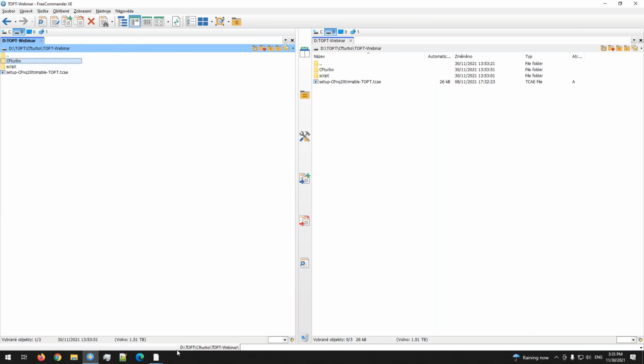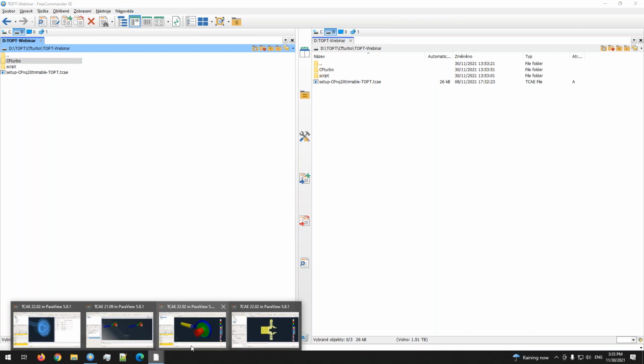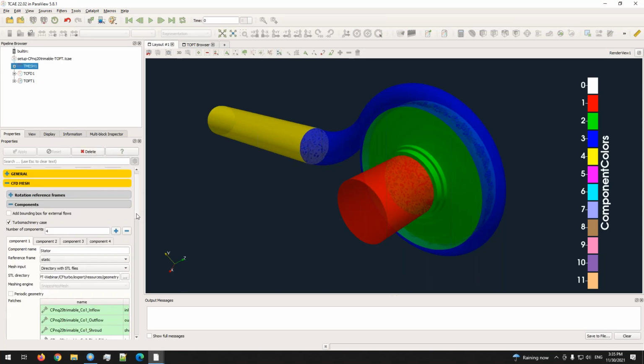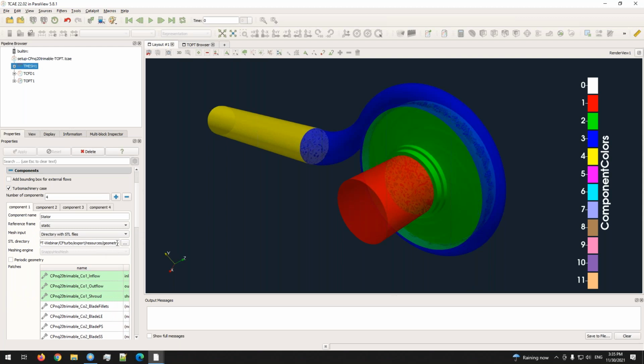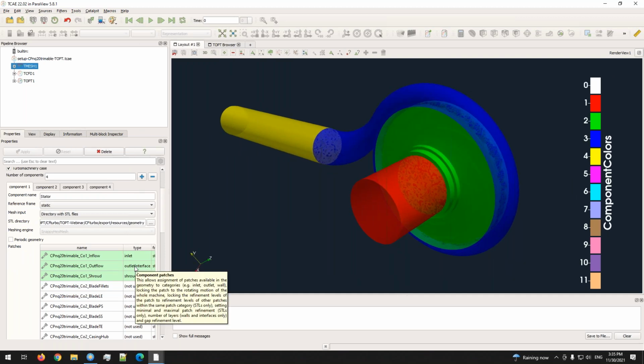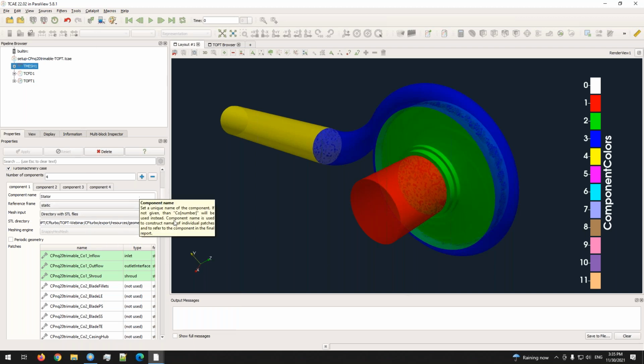Yeah, so if I go to my TOpt, which is here, basically in the tmesh we can see that the path remains the same. So we are in the CFturbo export resources geometry. So anytime the STLs are available, and for each run CFturbo gives us the new STLs for the new variants, and it can automatically be loaded. So we do not somehow adjust the path to the STLs. We did it in this way.